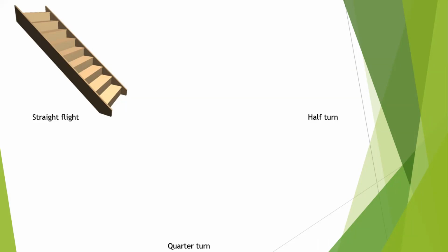Okay, so you should be able to cater for your deflection very well when you are dealing with a straight flight stair, because it is more prone to deflection because of the length of the stair. You understand what I'm trying to say? So the straight flight stair must be designed against deflection, and you should be sure of what you are doing before you specify. You have to design, get good specification, and when constructing, you must stick to your design.